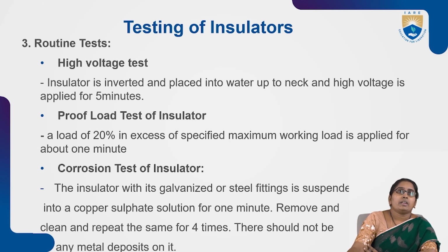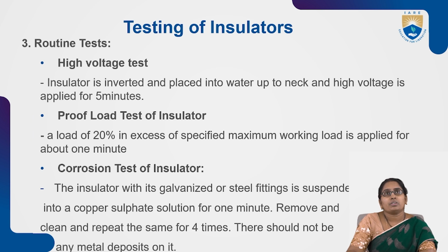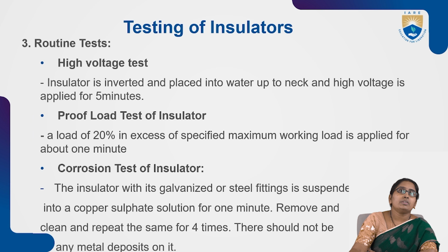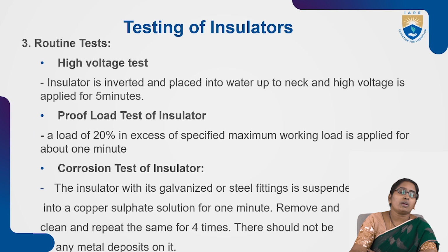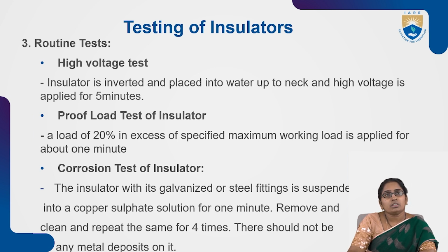Then, proof load test of insulator. A load of 20% in excess of the specified maximum working load is applied for about 1 minute. So that is what they do in this test.